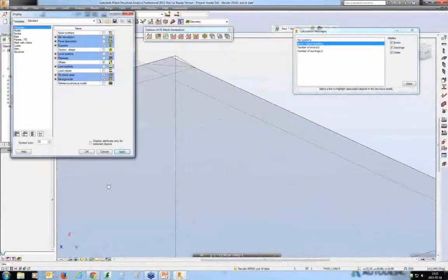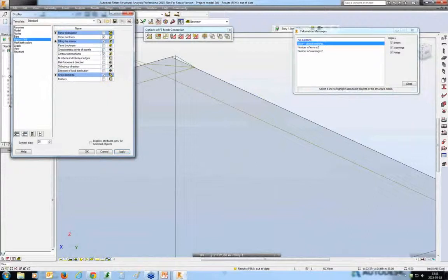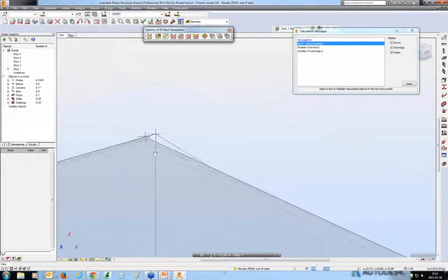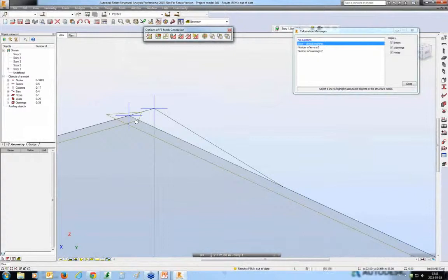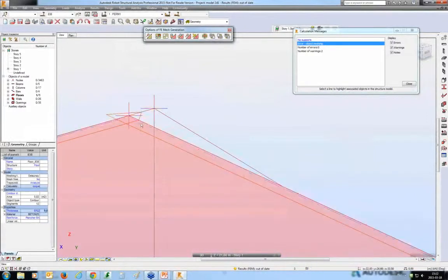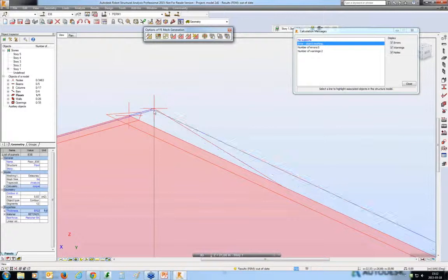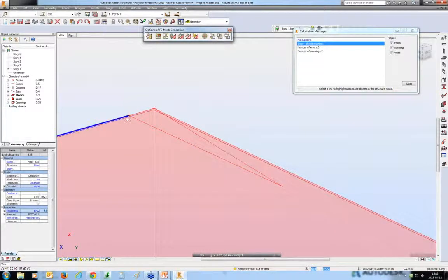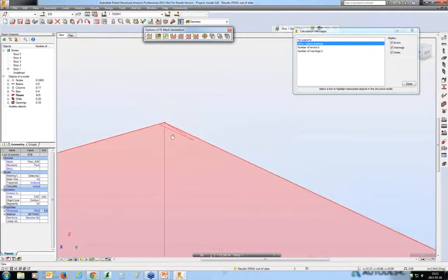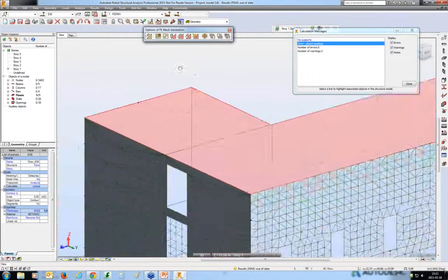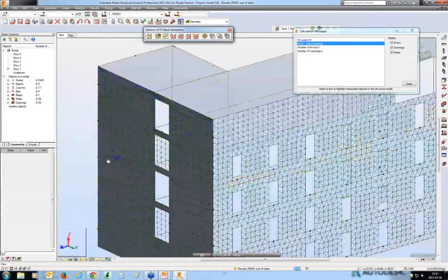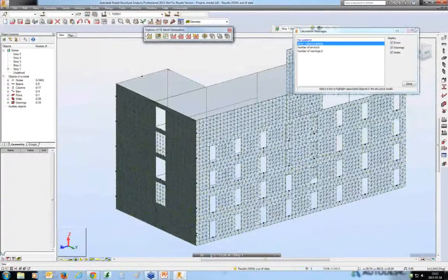I will switch the characteristic points of the contour, and I will move the contour graphically so that it is in the correct position. Okay, when you click on the contour and click again, you can drag it, and the same, I've got these characteristic points that I do not need to have, and I move it to the same location. So this is the first issue, and the second issue is with the opening.